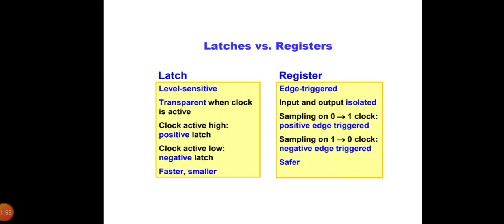They are typically built using latch primitives, and an often recurring configuration is the master-slave structure that cascades a positive and a negative latch. Registers can also be constructed by using one-shot generators of the clock signal or by using other specialized structures.